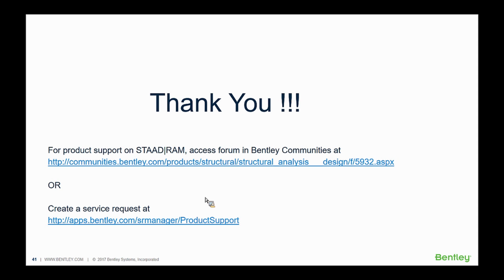A second question I have is, wasn't your 25% live load already included in your mass modeling load? Yes. So when I created the mass modeling, I included 25% of the live load and 100% of the dead load. And then when I combined the dynamic load with the dead load and the live load, we had the full values of the load. But as far as the computation of dynamic load is concerned, or response spectrum load is concerned, we did consider 25% of the live load.